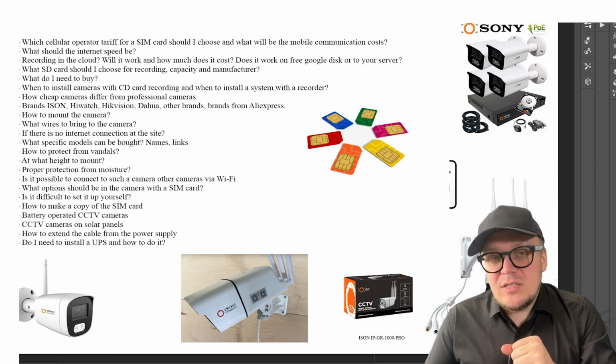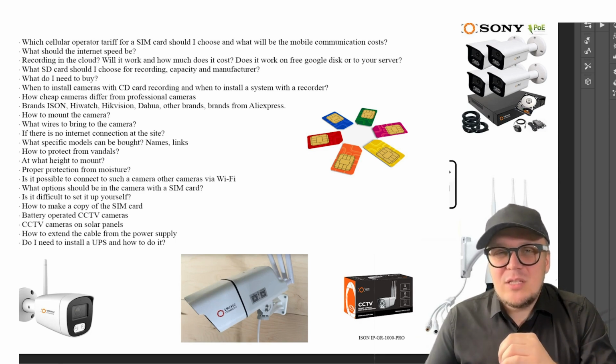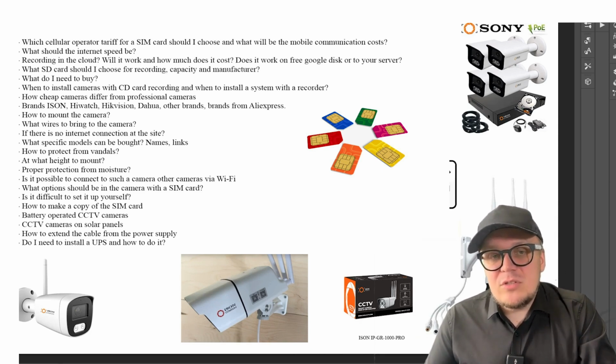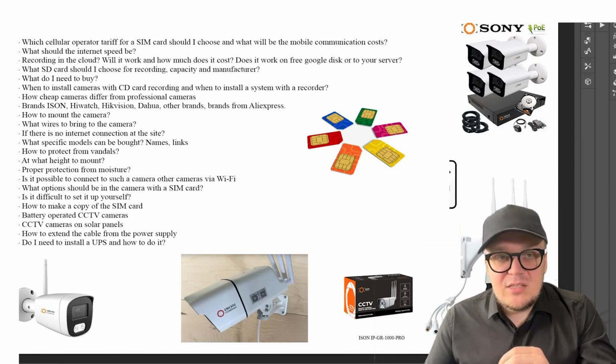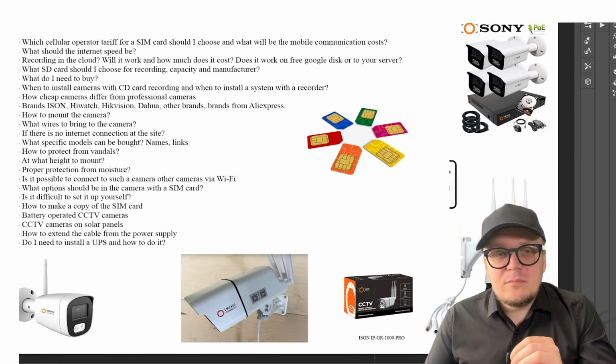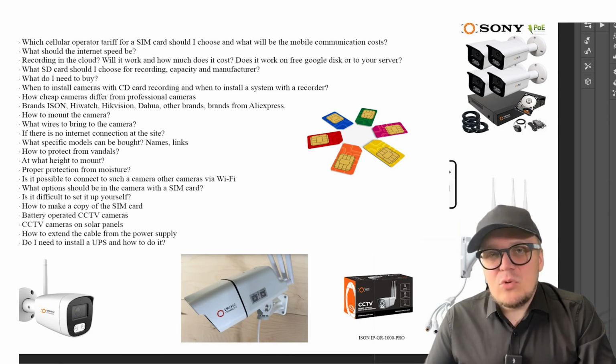Cameras with solar panels do exist. Firstly, you need to understand your region. Do you have enough sunlight? Secondly, it's very expensive. All those offers on AliExpress are of extremely low quality, both the solar panels and the batteries themselves. Proper solar-powered surveillance will cost several $1,000s. This needs to be understood. Any other option is likely to result in wasted money for you, because it will constantly be interrupted. The camera will constantly experience a lack of power. It will constantly malfunction because of this. So, yes, such a thing exists. But the region must be very sunny, and you should budget quite a significant amount of money for such a project.